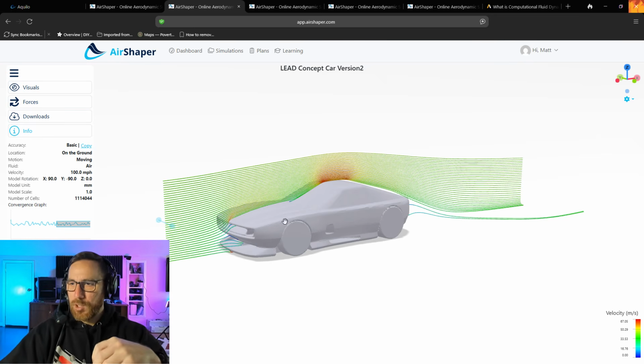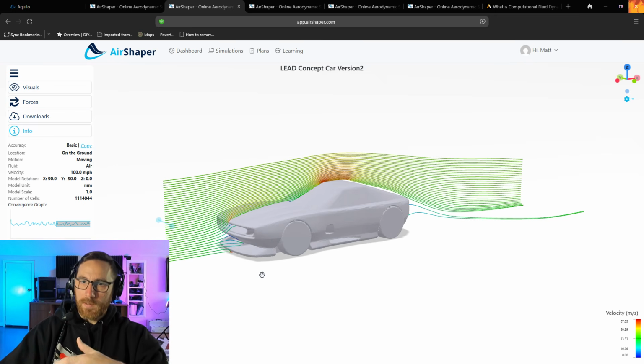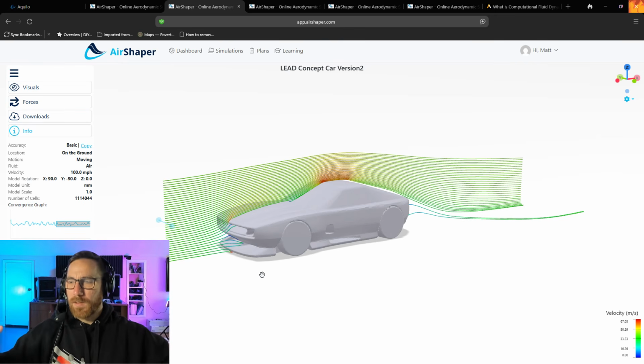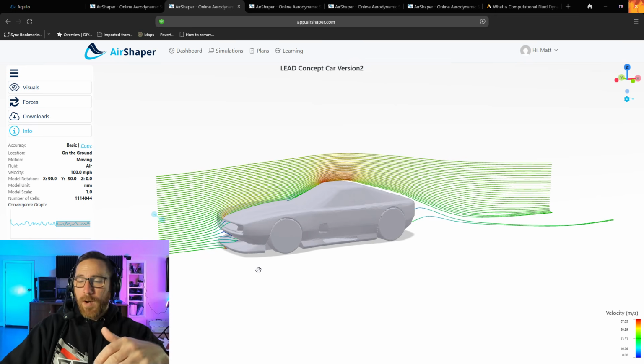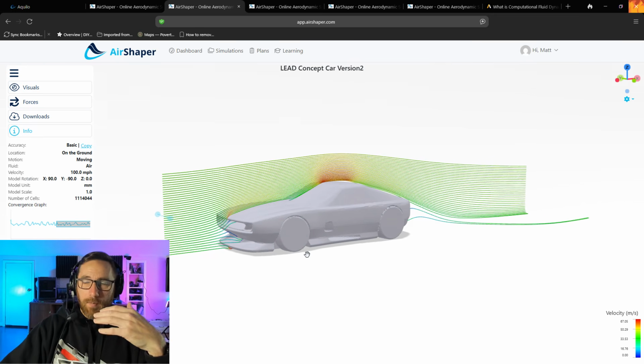So when we do simulation and we have a mesh on a body, it has to calculate what happens at each of those locations. And so the number of cells and basically the size of the boundary all have this impact, and then it continues to run these until it normalizes. And so with that process, that takes time.